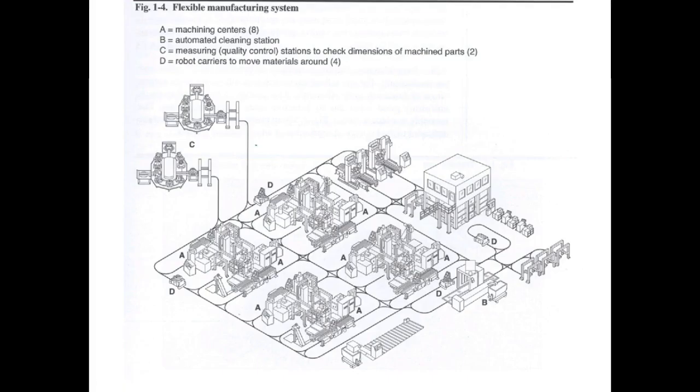Flexible manufacturing. This is a lot like a job shop, but the only difference is all the machines here are totally programmable, in what we call flexible manufacturing. We still have machines that do tasks, but they are all programmable. Does that make sense? So flexible manufacturing means I could probably run 1 part or 2 parts or 10 parts, depending on what the customer needs.